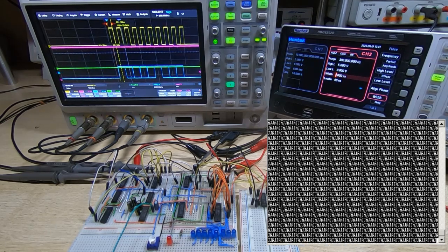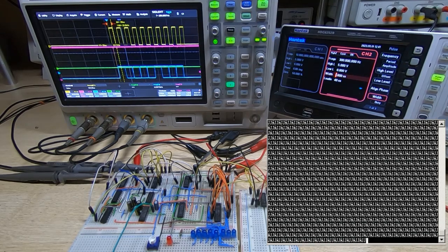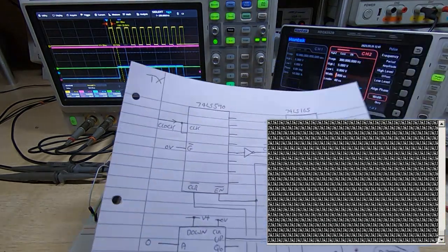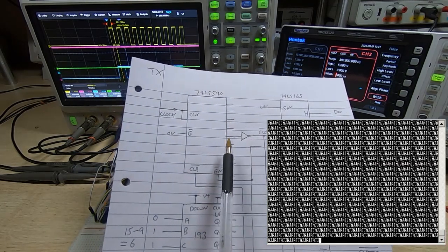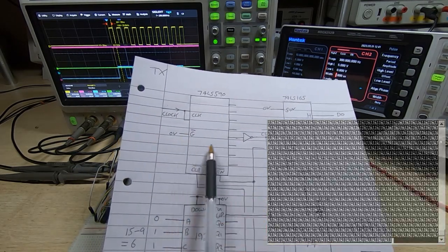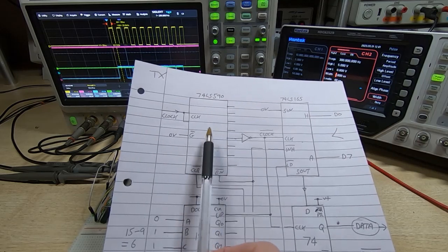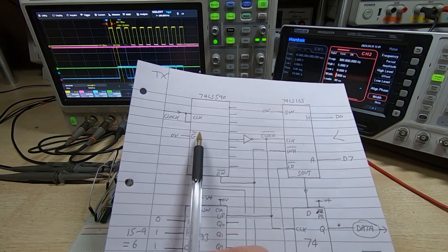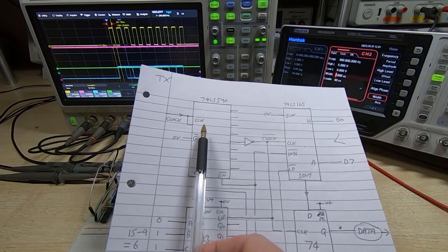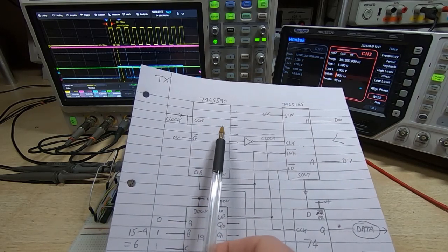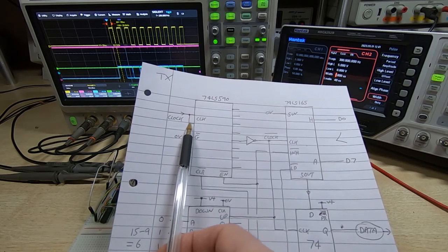So I'm just going to explain what's causing this, and it's a fairly simple thing, but it's again something that you need to be aware of if you're taking the systems level approach. This is the general circuit for this, and the issue in this case lies with this particular counter. This is a bit of an odd counter. It's got a counter and a separate register, and they're not updated in sync. So look, there are 2 clock inputs.